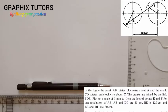Plot to a scale of 1 millimeter to 1 centimeter the loci of point E and F for one revolution of AB. AB and DC are 45 millimeter. BD is 120 millimeter. And BE and DF are 30 millimeter, right?